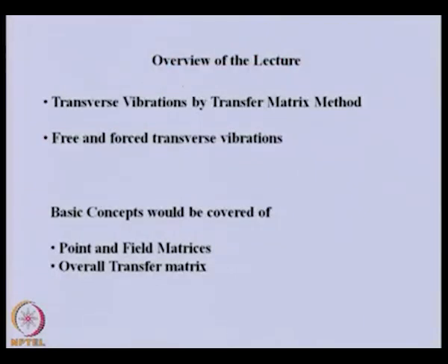So, transverse vibration by transfer matrix method, free and forced vibration both we can analyze. In this, similar to the torsional vibration case, we will be having point and field matrices development for transverse vibration, and similar to the torsional vibration case, we will be having overall transfer matrix concept, and then we can apply the boundary condition of the problem to either solve free vibration or forced vibration.